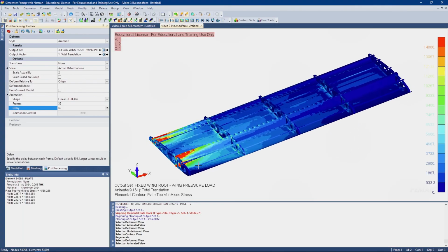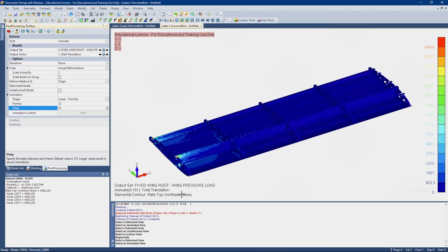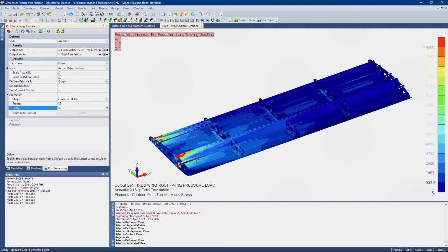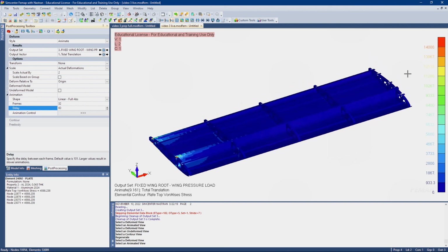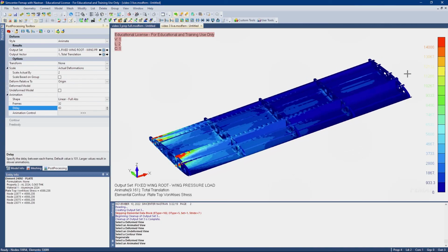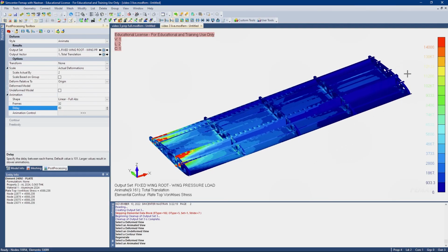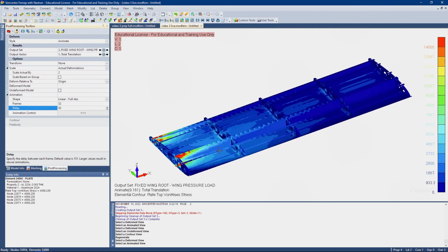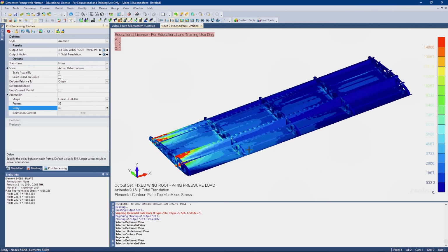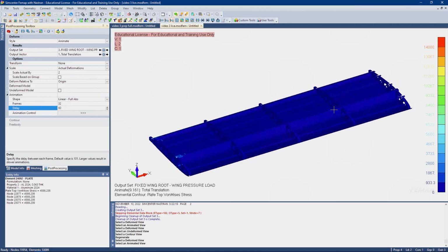The only difference is we saved ourselves a lot of work by just analyzing one section and then patterning all the way down. If you can't do that, then you just have to go section by section and mesh the whole wing, which can be very time consuming, but the techniques and everything are all the same. So if you wanted to do that, you certainly could. But just for time constraints, this works in getting us a pretty good looking finite element model. And hopefully we can learn something along the way.